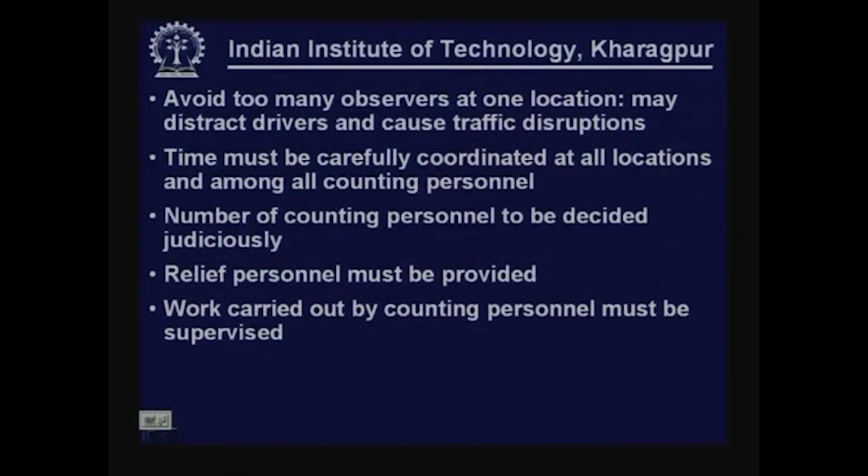The number of counting personnel is to be decided judiciously. It is very difficult to give a rule on how many persons will be required. One should basically go to the field and see at what level he wants to collect the data, or it is necessary to collect the data, how many vehicle types, how many approaches, how many traffic lanes there are, what the traffic volume is, and what the average shares of different vehicle types are in the total traffic volume. Then one can decide how many persons will really be required to do the survey or the studies in a proper manner with the desired level of accuracy.